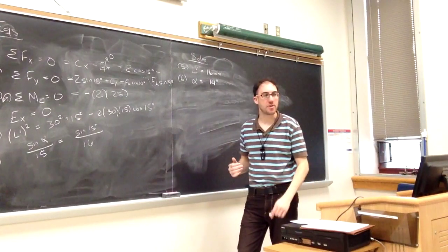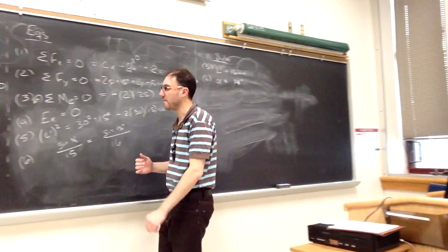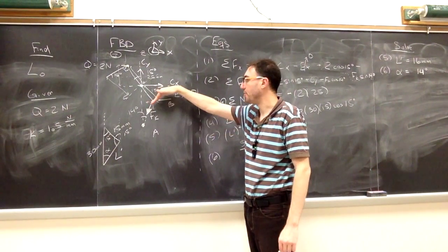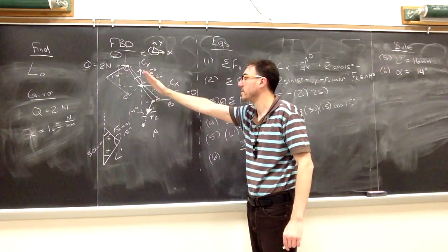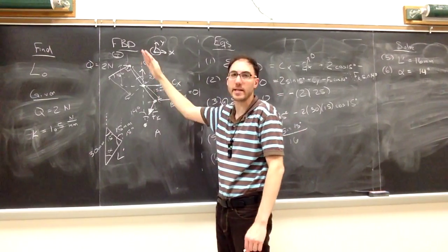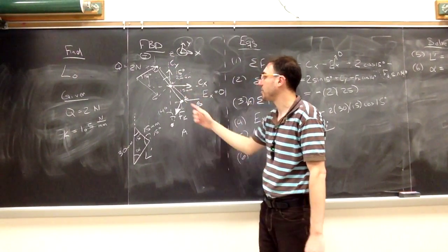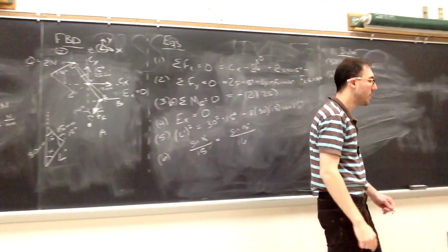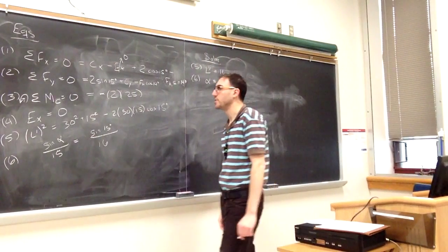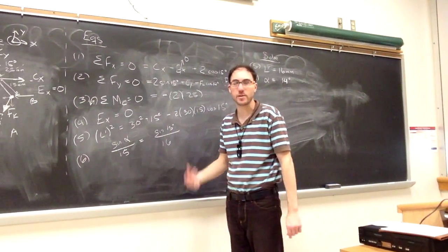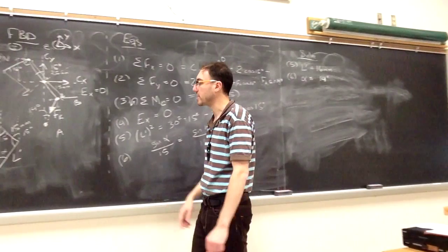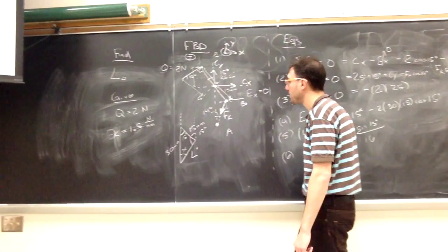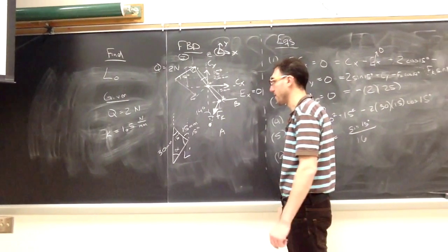The harder part though is the spring force at F, or applied at B, because this is not normal to the angle from DCE or DCB. So I can't just multiply it by 15 the way I was able to multiply the 2 newtons by the 25. This one I do need to break down, unfortunately, into its components. But again, I need to do it carefully to make sure that I have the right sign on everything, the right trig sign on everything.